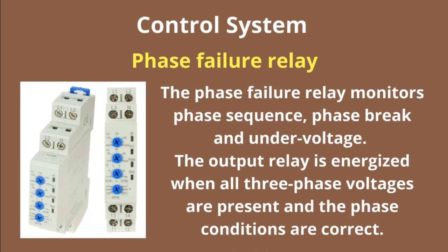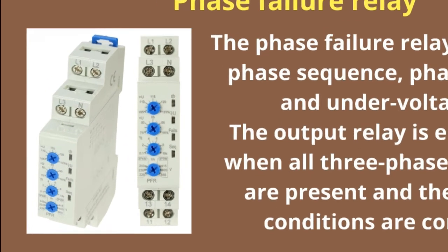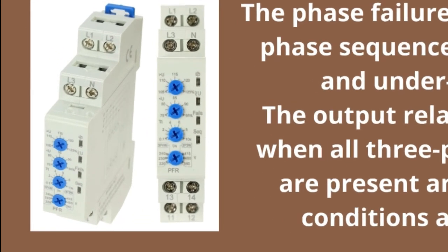Phase failure relay. The phase failure relay monitors phase sequence, phase break and undervoltage. The output relay is energized when all 3 phase voltages are present and the phase conditions are correct.